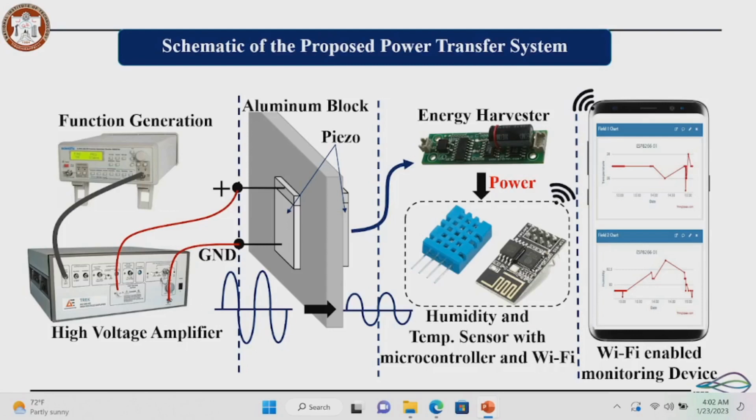So we found this component, and the problem with this component is very low current. But it can be used in future to charge supercapacitors and all. So we have to design one capacitor or supercapacitor circuit which will charge using the ES300. But right now in this scope, we used the ES300 to directly power two very low power devices, the ESP8266 and a DST module. We made one PCB, connected these two on the same PCB, a very small module, and we transferred the data over the internet, over Wi-Fi.